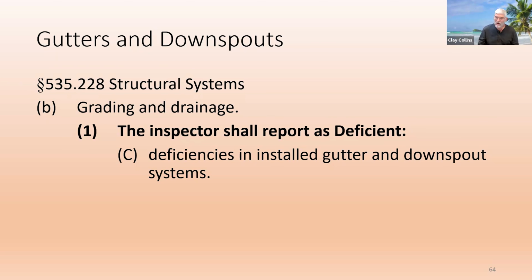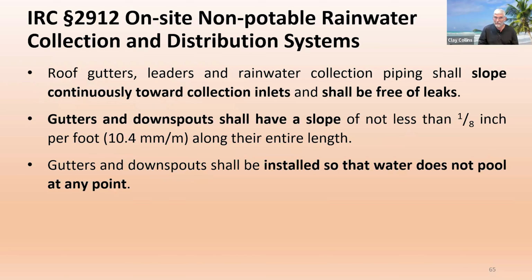But if the gutters are there, other than simply recommending more, or that they be installed, or that they be replaced, we have to look at, are they installed correctly? They should slope and be free of leaks.